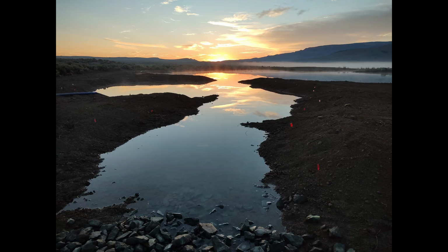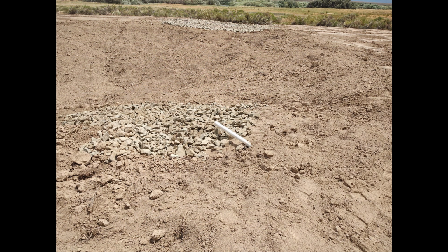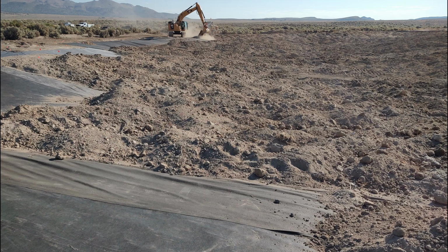I helped build a fishing pond that was 1.3 acres in size in the desert of western Nevada. We also built a stream that was 200 feet long and a small wetland that was 60 feet in diameter. Here's how the small wetland appeared the day it was finished and before it was filled with water. We used aquatic safe liners that were covered with thick layers of soil to build the fishing pond, the wetland, and the stream. We used the liners because the texture of the soil was low in clay and the groundwater was way below the surface.